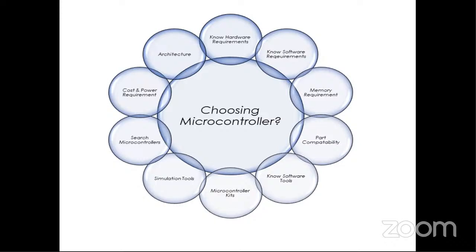Along with that, we should be familiar with the architecture, what type of hardware and software we require, and the simulation tools we need. So memory requirement, power consumption, timers, and how many ports can be interfaced are the basic aspects when you choose any microcontroller.